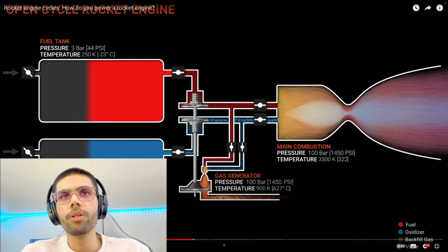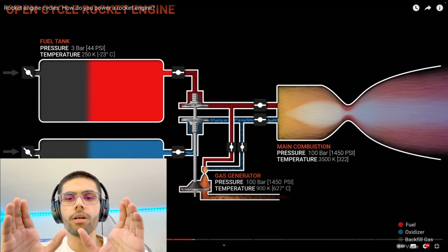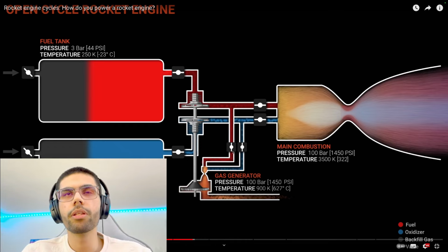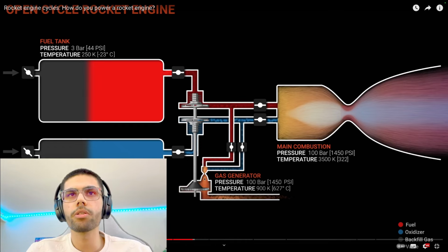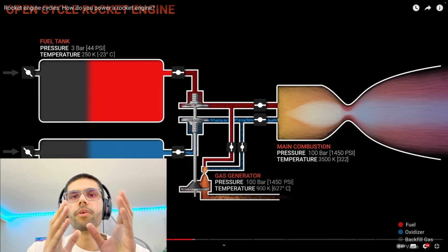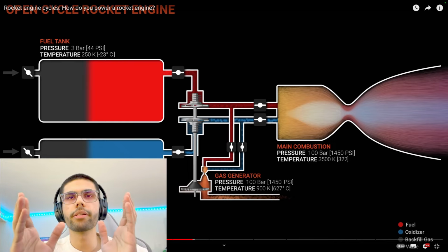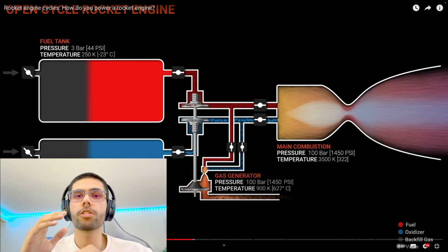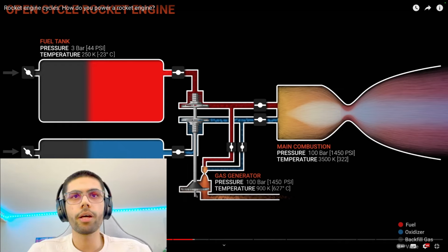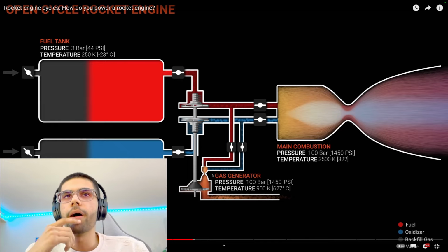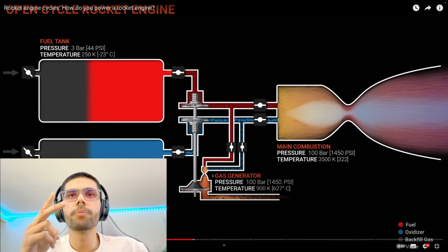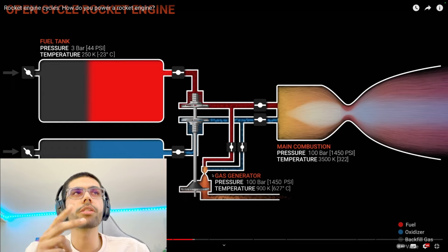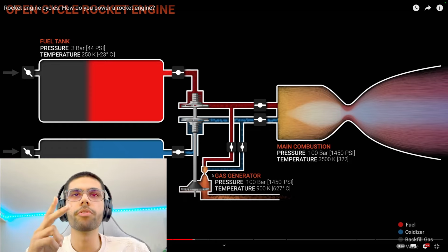So what we do, instead of controlling these valves to make it a stoichiometric ratio, is deviate the ratio of fuel to oxidizer from the stoichiometric ratio in order to make this reaction cooler, so that our turbine blades could actually survive that. Now this brings us to two possibilities. It could be either oxidizer rich or fuel rich.